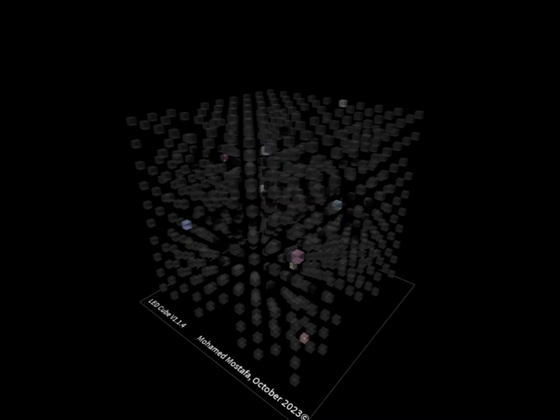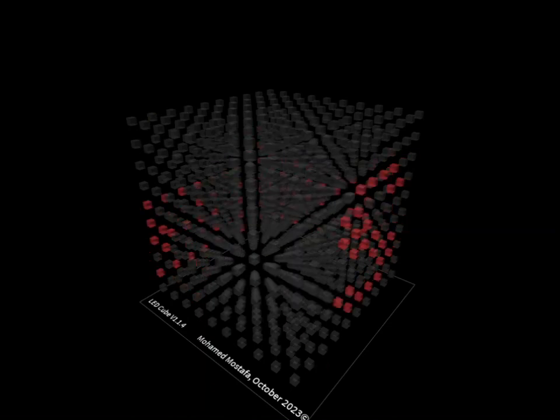The multiplexer is built by using a component called a latch or a flip-flop. We will call them latches from here on. This multiplexer uses an 8-bit latch IC called 74HC574. This chip has the following pins: 8 inputs, D0-7; 8 outputs, Q0-7; 1 latch pin, CP; 1 output enable pin, OE.